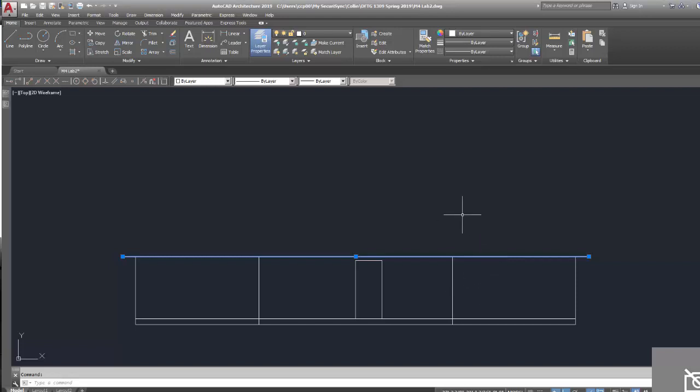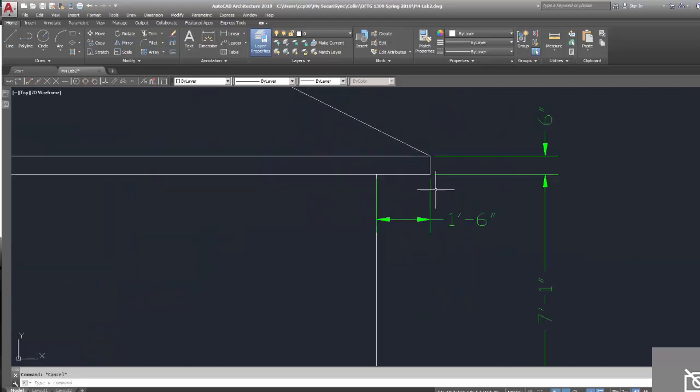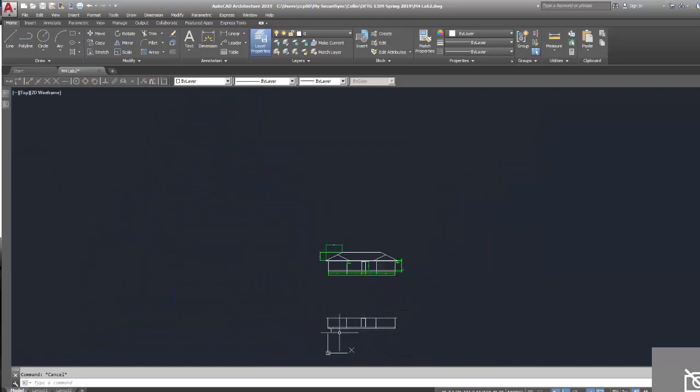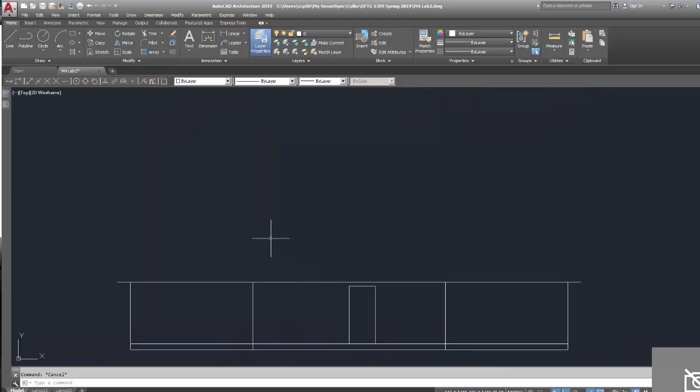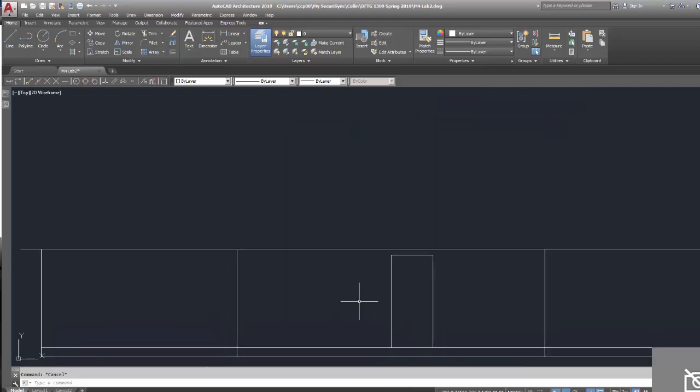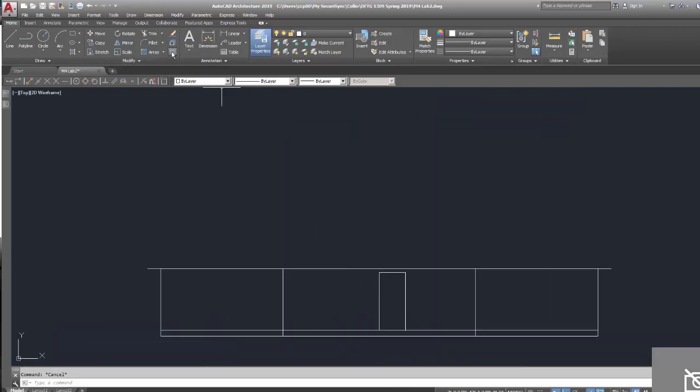It looks like from our roof, there is a 6-inch eave there. So we're going to go ahead and offset this line 6 inches. Yeah, that's a big difference there. So we'll go back up to the offset command, and we load up 6 inches as our distance. I click on the line, drag my cursor up above the line someplace, anywhere, left click anywhere, our line's drawn.